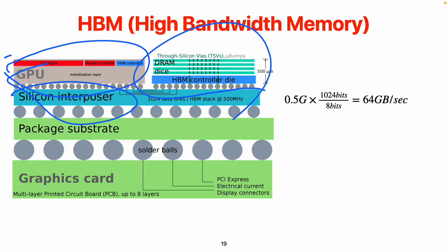So I would say high bandwidth memory is a very brute force technology, in a way that we don't actually invent anything. There's no innovation here, to be honest. The innovation is from the hardware side, from the manufacturing and packaging side, that we make the wires smaller. And then we just brute forcefully give you wider bandwidth, wider bit width in a bus.